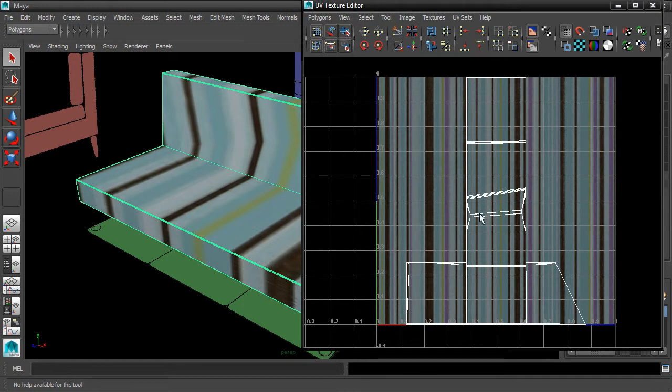This is why we get so much stretching and why it's way too large. What we want is a UV layout that shows this little fabric swatch as being pretty small on these surfaces. So we could scale this directly if we want. We could right click and choose Shell and then select, and now we've selected all the parts. All the connected parts are shells. And then scale it with the normal scale tool.